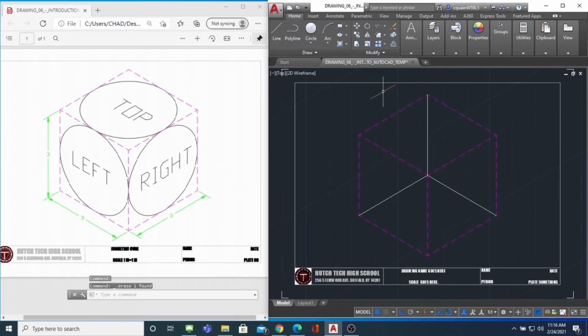So what we need to do instead is create an ellipse that will work for us. The way we're going to do this is go into the ellipse command, E-L-L-I-P-S-E, and it helps if you spell it right. Now it's giving us choices. It's saying specify endpoint of the ellipse, or do we want to create an arc, a center, or an isocircle? Isocircle sounds like something that Mr. Q just mentioned before. So I'm going to click on isocircle.